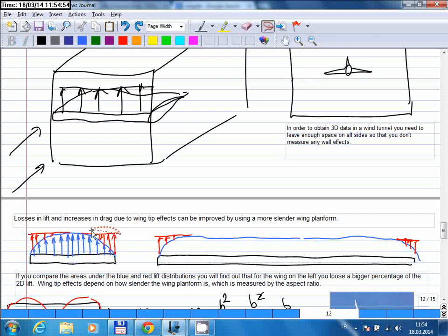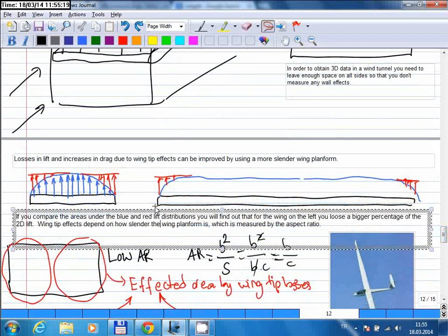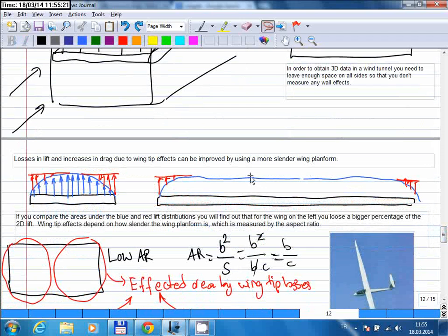And these are the differences between them, right? So these are losses. These are the lift forces that you lose for having a three-dimensional wing. As you see, comparing the two, you can make these losses due to three-dimensional effects better by using a very high wingspan wing like this one here. So if you extend the wingspan as much as possible, then the area where you lose lift force will become smaller, as you see here, right?